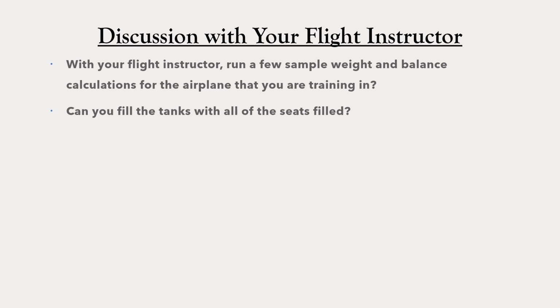Can you fill the tanks if you've filled all the seats? In many general aviation airplanes, if you put a reasonable sized passenger in every seat, you don't have enough useful load left to fill the tanks up with gas. You need to know if that's true for the airplane that you're using.